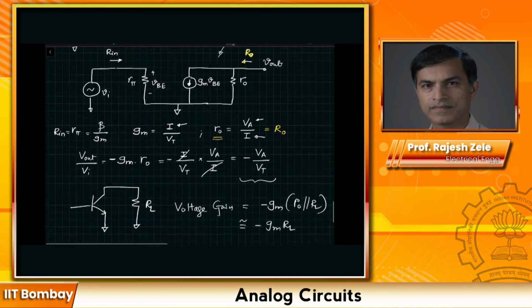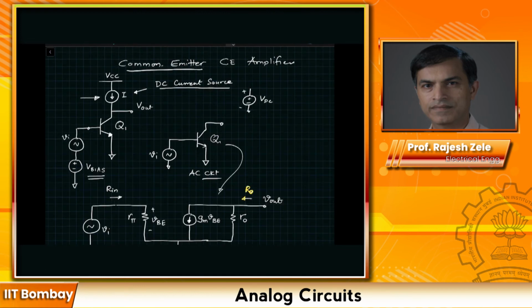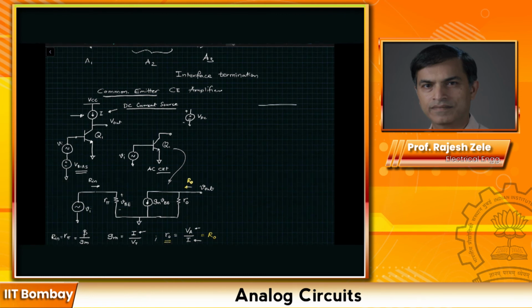One quick thing to note here is, how do we get this DC current source I? Using another bipolar transistor. Follow my train of thought, we could simply get a PNP transistor and we can connect some kind of DC voltage source, plus minus VEB, over here. And what does this look like? This represents a current source, because the current which is going to flow through this I is given by IS times exponential VEB divided by VT. Again, these are PNP parameters.